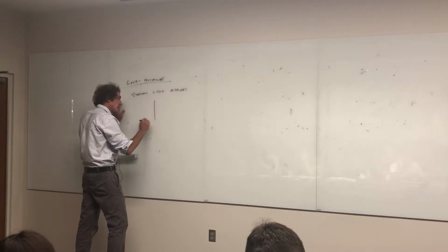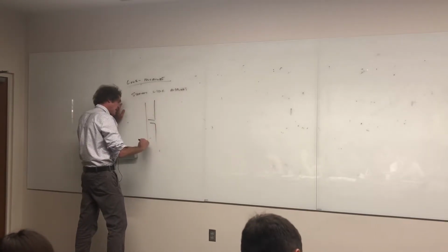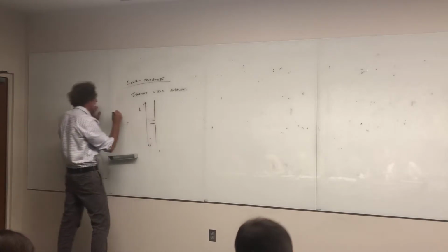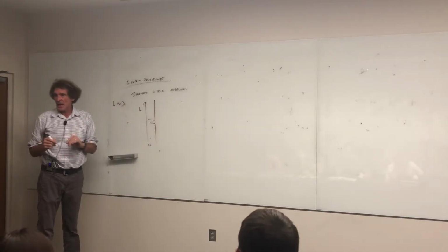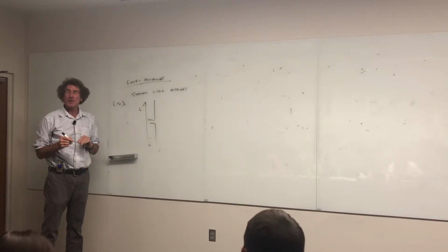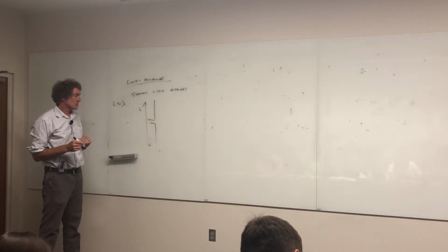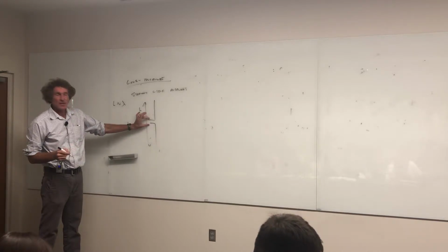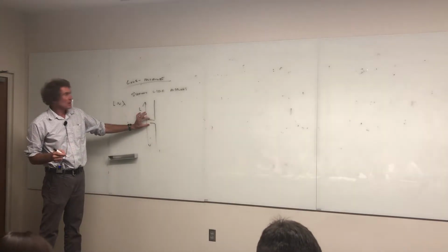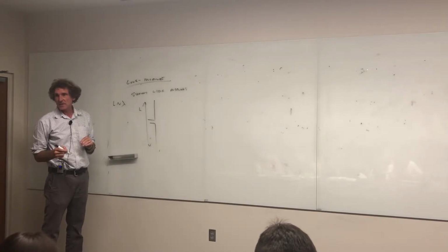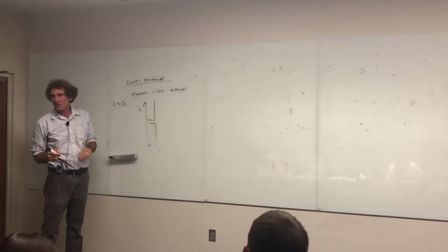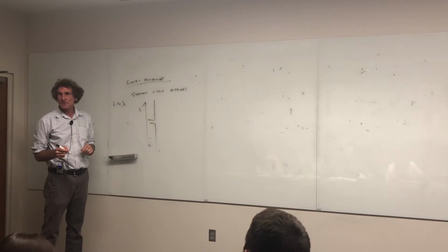So for this, we're going to have an antenna of a length L. But now L is of the order of a wavelength. Typically half wave, three-quarter lambda dipoles are typical. They're almost always center fed. They don't have the feed up here or the feed down here. It's not that you can't. Some people do that for very odd reasons. This is the way most antennas appear.